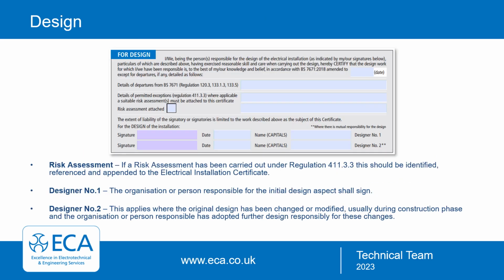Next we look at the design section of the certificate. If a risk assessment has been completed, it should be noted, referenced and appended to the electrical certificate, and this may be for omission of RCDs, for example. It's important that that risk assessment is attached to the certificate.